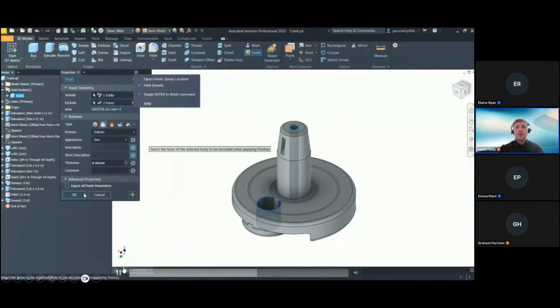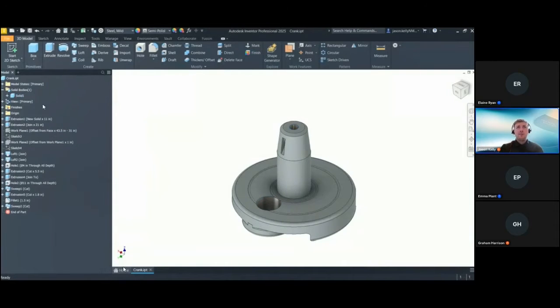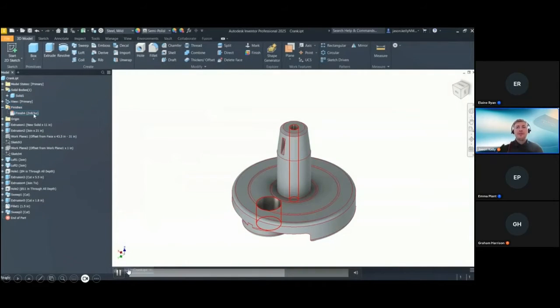One of the other functions they've added once you've completed the command is you can now show extended names. If you're not aware, show extended names will give you some more detail about the particular command that you're in. If, for example, you're creating your extrusions and your lofts, you'll see if you go to this little 3 lines menu, you've got a display preferences option and you can turn on show extended names. That's something that I'd recommend to everyone. But what you've now got, rather than it just saying finish 1, finish 2, finish 3, you can actually see what finish has been applied, and as you hover over it, what particular faces, with the faces that aren't turned on highlighted.